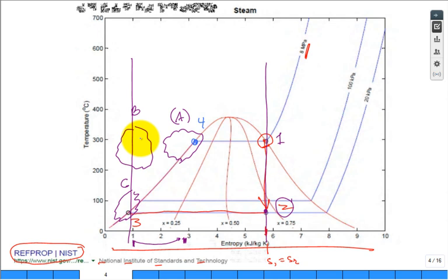Now, let's take a look. What's on the y-axis? Temperature. About what temperature was the condenser? Do you remember the numeric value at 20 kilopascal? Can you visually see roughly what it is? Give me an estimate, nearest 5 degrees increment. 60 degrees is the number it is. 60 degrees C. That's still pretty warm.